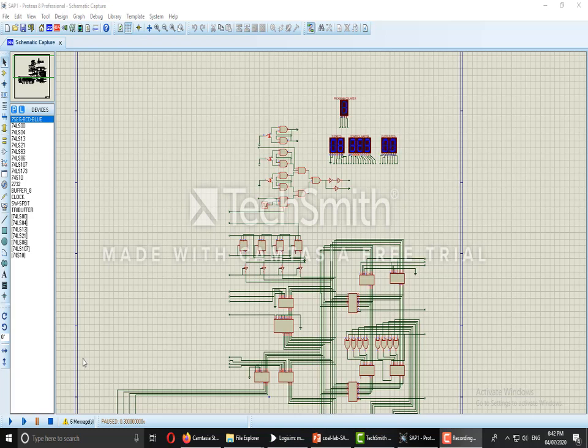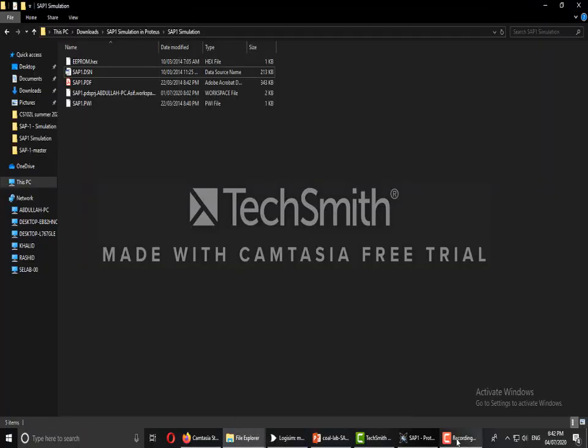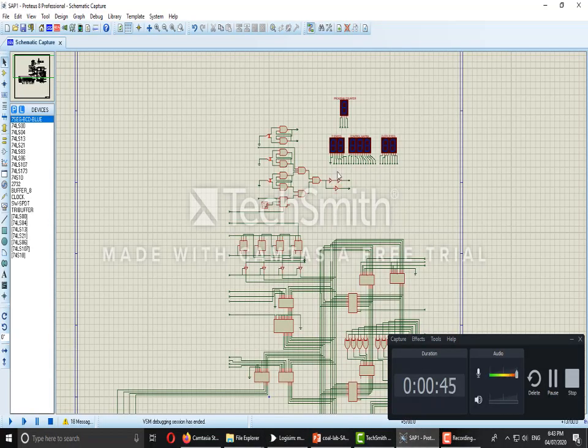We can either run the simulation as a whole, but it would be very fast and probably it won't be easy to understand. Let's see. You can see the program counter values are incrementing, the T states values are changing, and you can see the final output at the output display. Or you can see what happens at each clock tick one by one.